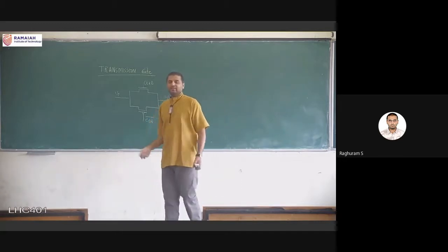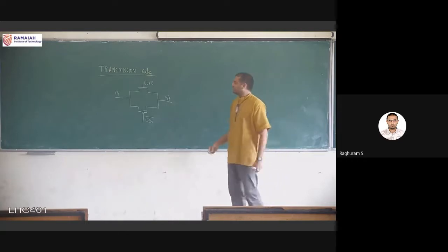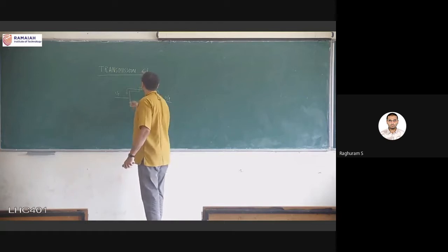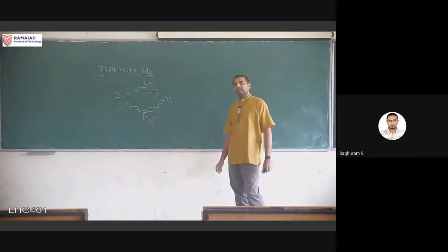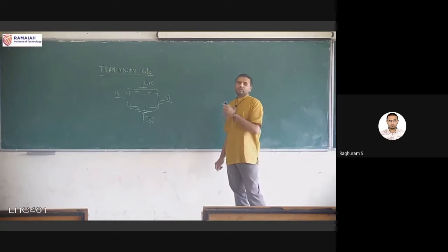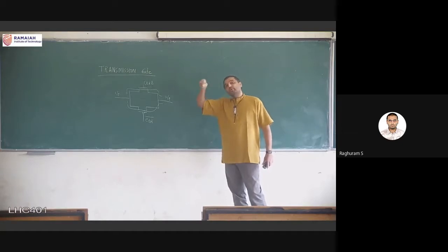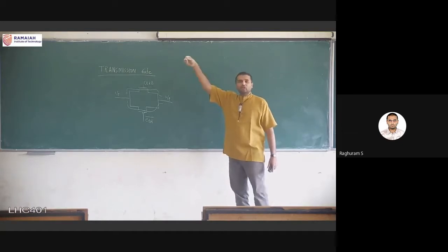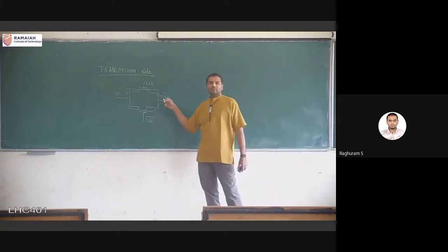Both are acting as pass transistors only, but now we have the ideal case, because if the 0 is there, it will get conducted through the NMOS transistor ideally. One will get conducted through the PMOS transistor ideally. So even though the NMOS transistor will turn off at 1.6 volts, from 1.6 to 2 PMOS will be conducting. It will connect the output all the way to 2 volts. So that way we can achieve the best values at the output.